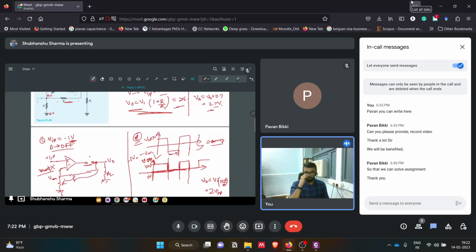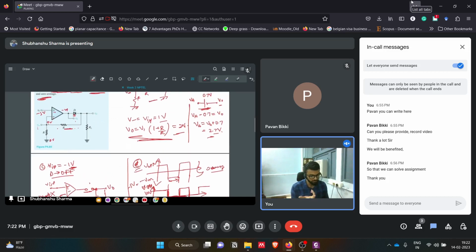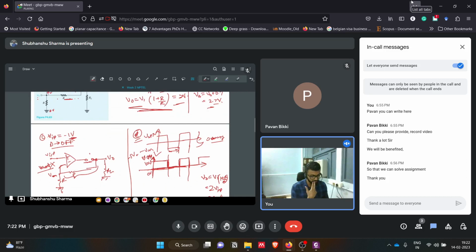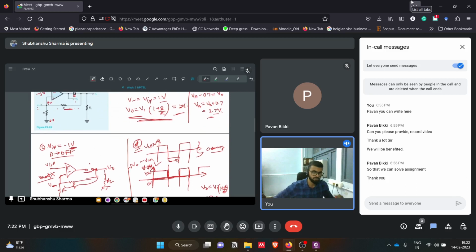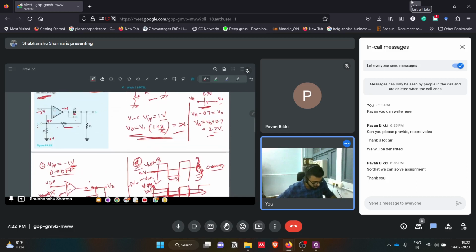So now you think, this circuit was giving a gain of 2, and this is what it did with a square wave. For some applications, if you need this square wave to be not symmetrical, and you want to shift the DC bias, which here is 0 volt, to an upper value, then you can use this circuit.